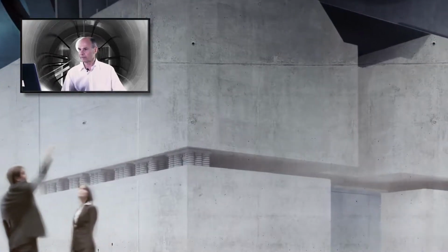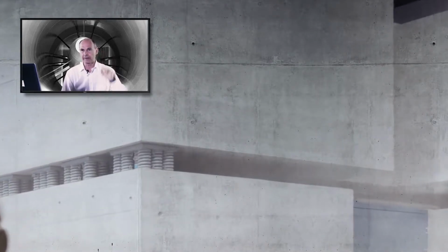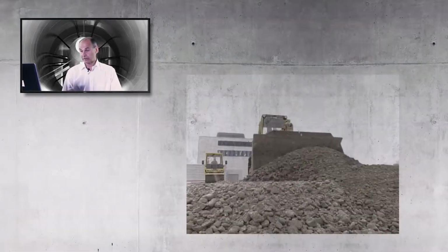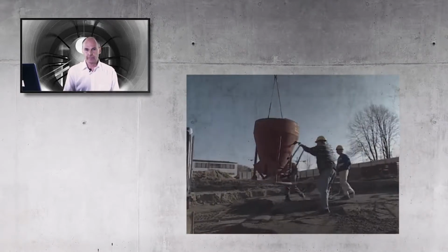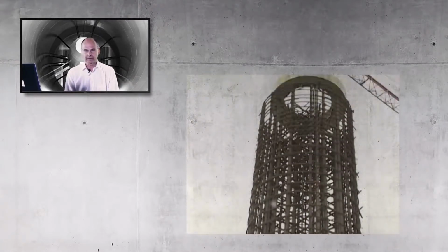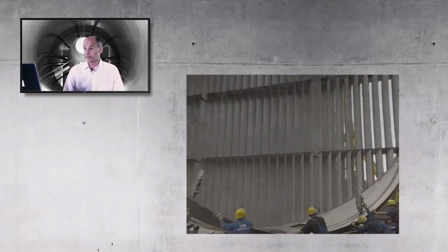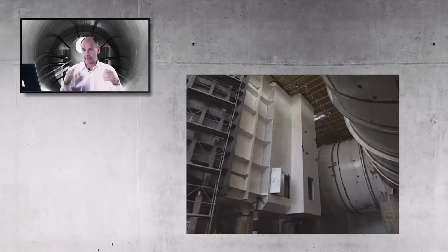If you physically go into our wind tunnel and look at where the fan is mounted, you literally see springs supporting the seismic mass. And then the foundation for the fan is a separate foundation from the rest of the building. It sinks down into the ground a very long way, and there's a soft connection between it and the rest of the building. The vibrations are relatively small, but you don't want them to go into your building, and in particular you don't want fan vibrations to shake your model, so you have a separate foundation.